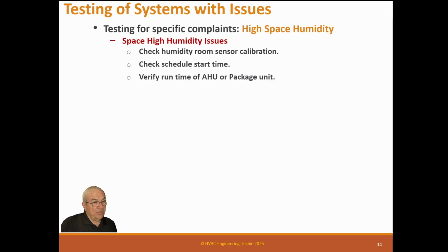When it comes to humidity, package units are the very worst. What happens a lot of the time is they have way too much capacity, so their runtime is short, and they don't dehumidify the air enough to drop down the humidity level. So in those cases, you have to lower the airflow on the package unit. You can only go so far, though. You lower it to get as long a runtime as possible, and to make sure the air is colder across the coil. And less airflow will do that.